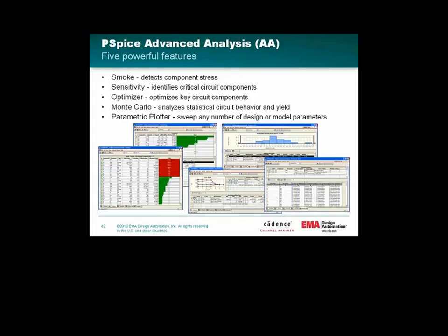You can get that information from the data sheet, put it into our model, and you're going to be good to go. Then you simply run a simulation in PSpice like you normally do and say, run smoke on that simulation. Tell me how far I pushed my components. So is my resistor using up 2 watts when it's supposed to be a 1/4 watt? And it's going to tell you stuff like that. So very, very useful information. We find it especially popular with military and aerospace, but really anyone can benefit from that.